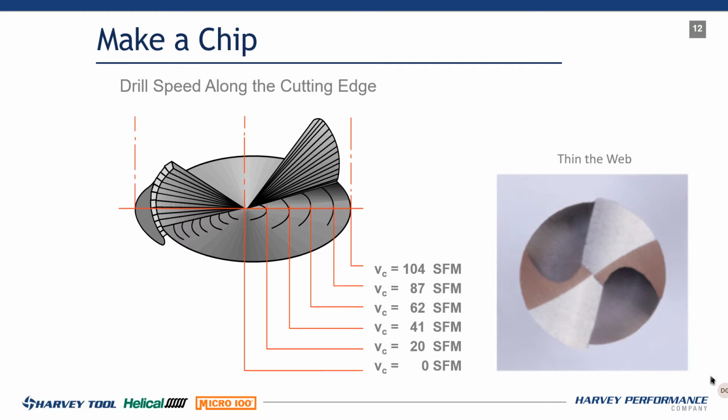Number one is we're eliminating the thrust force on that drill by actually splitting it, which gives you a primary cutting edge and it gives you a secondary cutting edge. That's number one. Number two is we're helping self-center that drill. That drill is going to self-center a little bit better by splitting that. Okay. And number three is we're actually breaking up the chip. It acts like a chip breaker so we can get manageable chips.